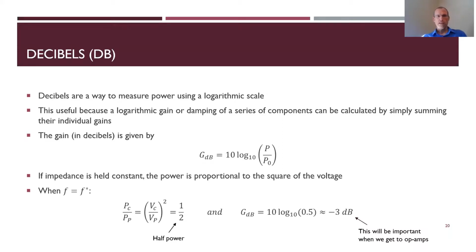You want to know the gain in decibels. Generally decibels is a logarithmic scale, as I said, log base 10. For decibels, you multiply by 10. And in this case, it's power, so power divided by my input power, whatever's coming out divided by whatever's going in. Log base 10 of that, multiplied by 10, gives you the answer in decibels.